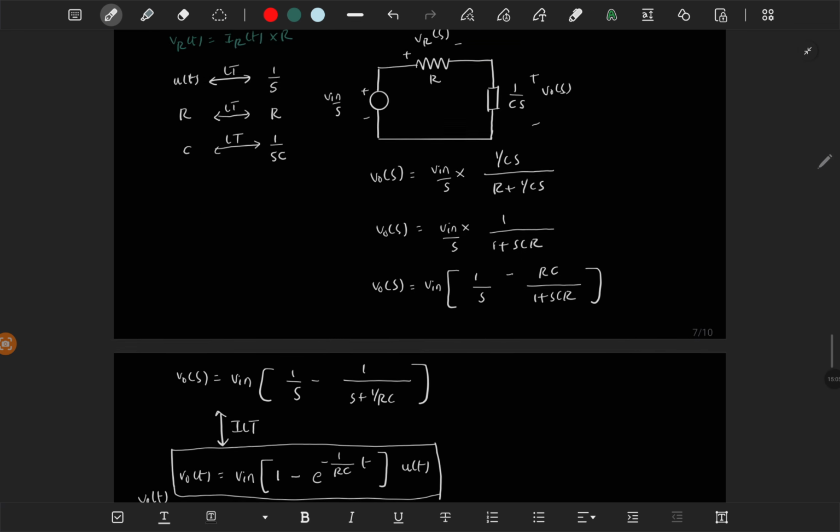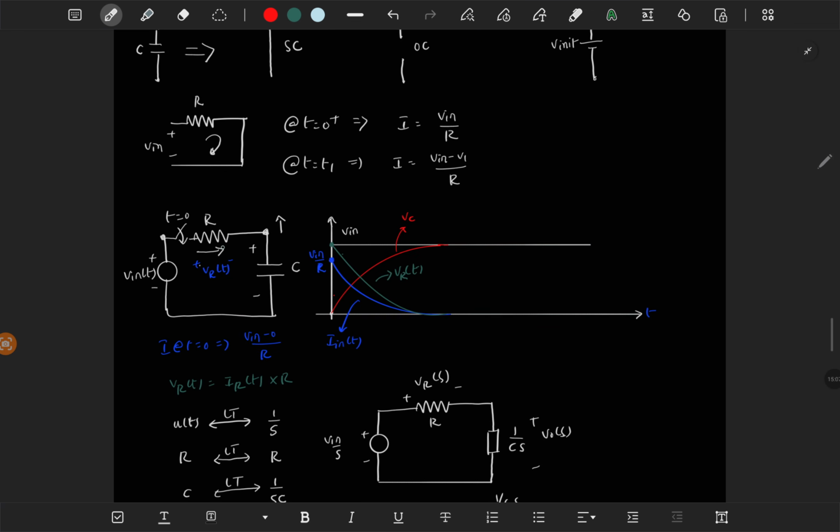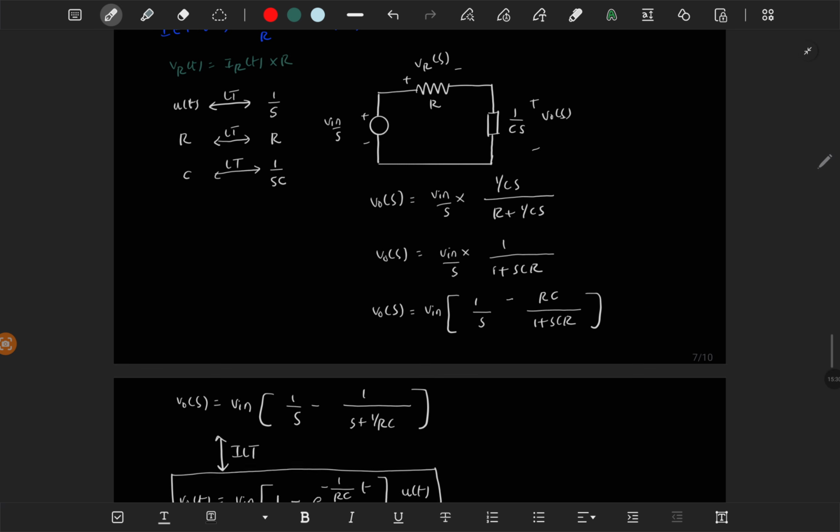So in a series RC circuit, we have directly R into C, because if you look from the two terminals of the capacitor and replace the input voltage with a short circuit, you are left with only R. So R equivalent is simply R here, and there is only one C. So R into C is the time constant for this circuit.